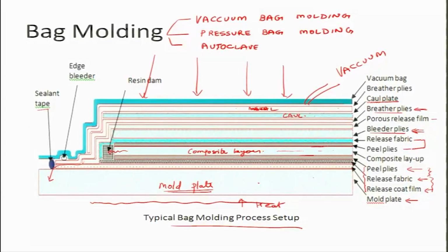and we will explain autoclave molding later, but let us look at these two pictures. So, vacuum bag molding is very popular, so is autoclave molding. So, between these three, vacuum, pressure and autoclave, pressure bag molding is more expensive, and the reason it is more expensive is that you have to make specialized tools for each particular shape.